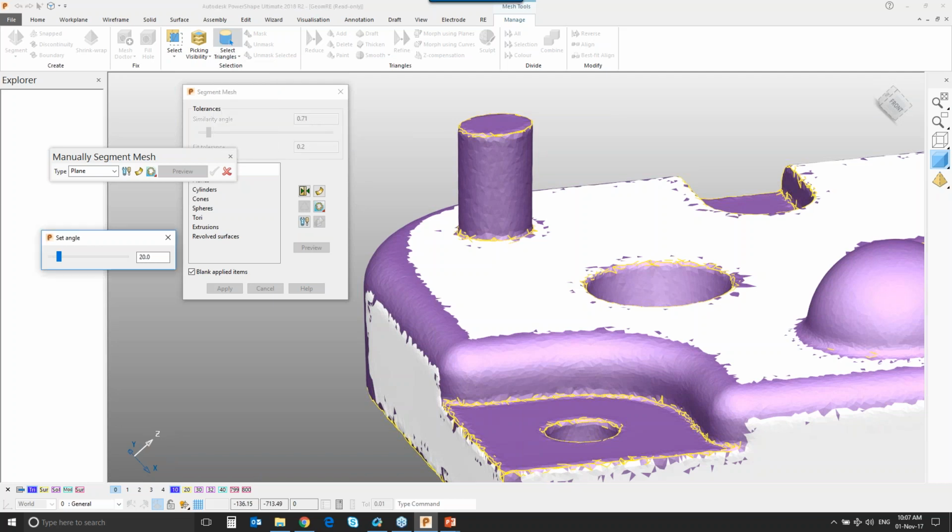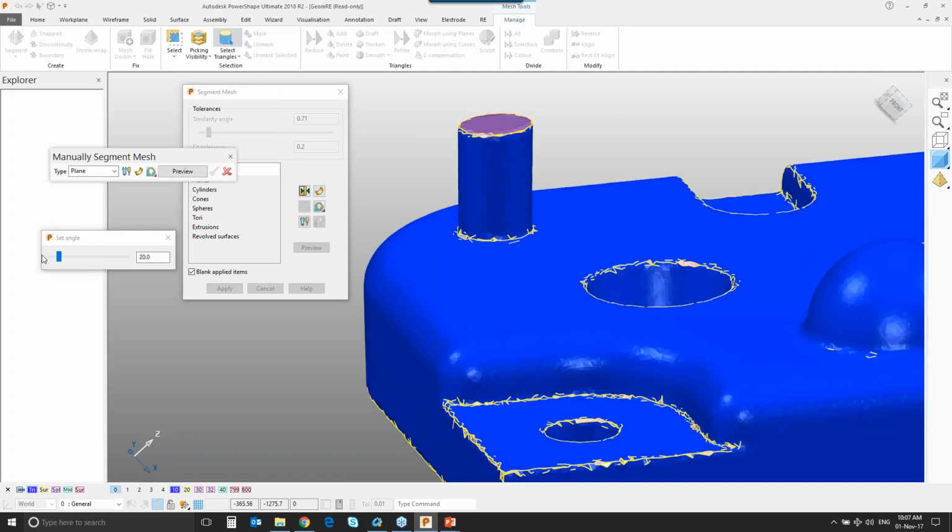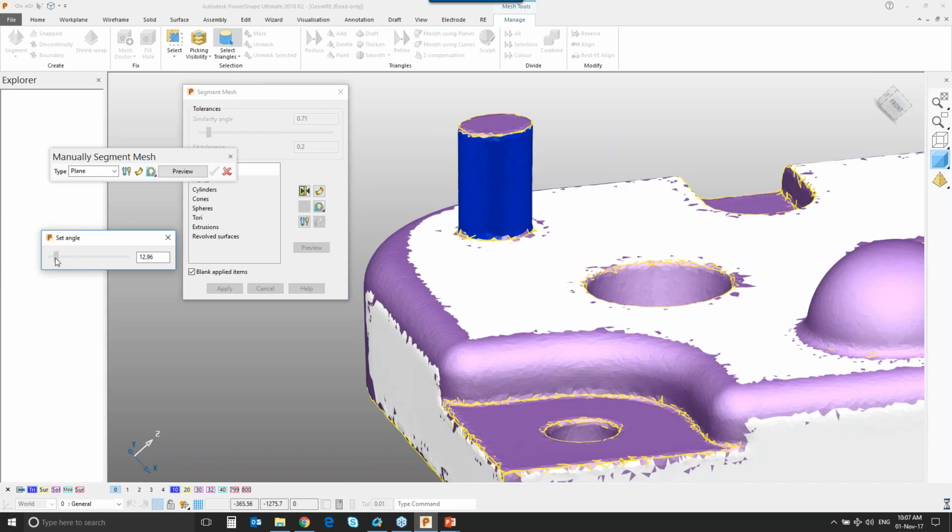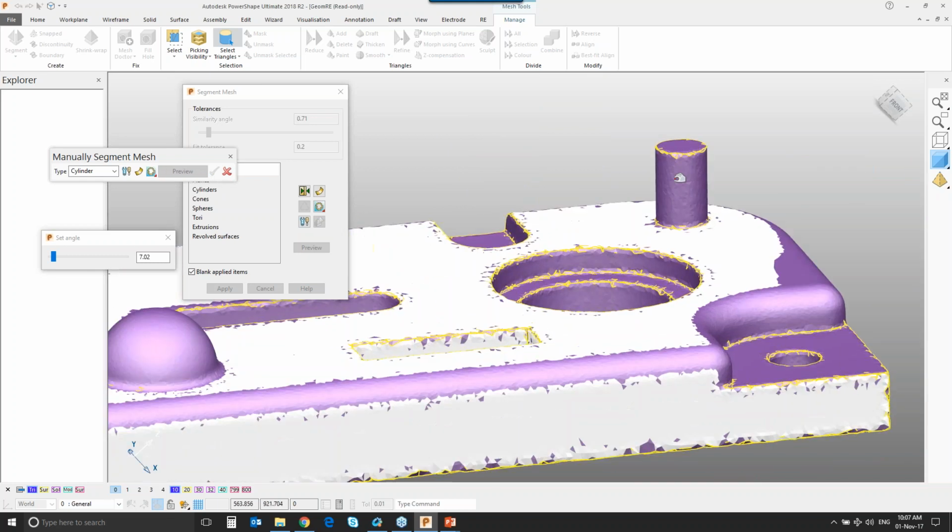So now it will look for sharp edges and stop at those, depending on the criteria I've got set on this slider. So you can see here I can detune that and say, okay, that's the area I'm looking for, and it's not a plane, it's a cylinder that I need. And sure enough, you can see that I have my cylinder, which I can keep. Repeat the process over the far side here, and immediately it gets the cylinder region that I want.